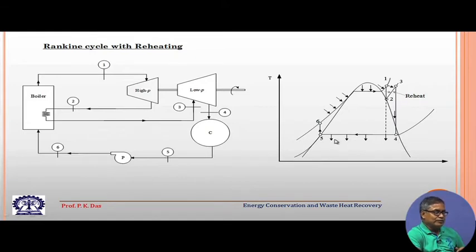And as usual we will assume that the condensate that comes out of the condenser is at the saturated liquid condition, and then it is taken to the pump at a low temperature, low pressure, and then the pump raises its pressure up to 6, and then it goes to the economizer. This part is the economizer part, and then this part is your evaporator part. If you remember the schematic diagram of the boiler I have given at the beginning, and then again it is the superheating part.